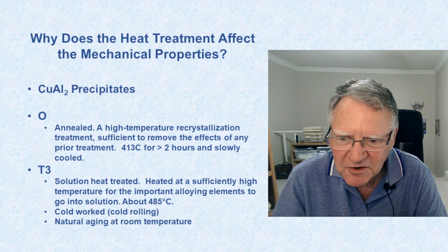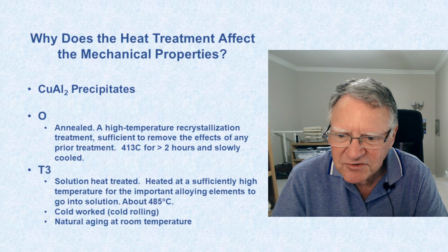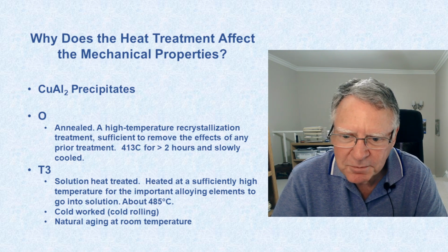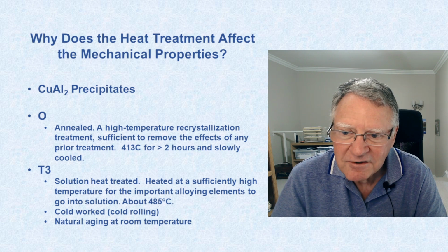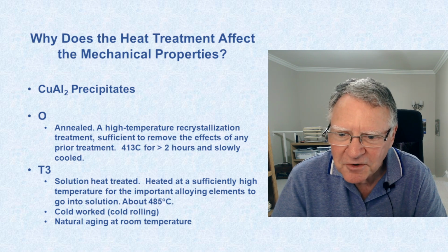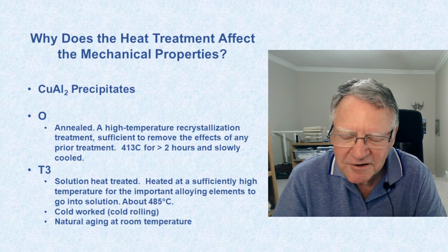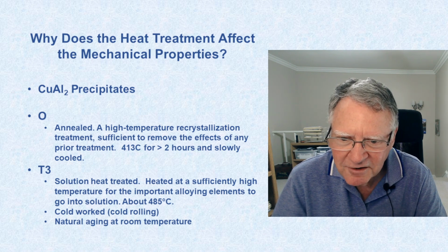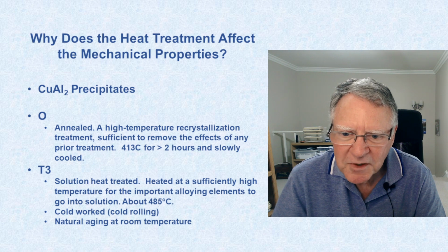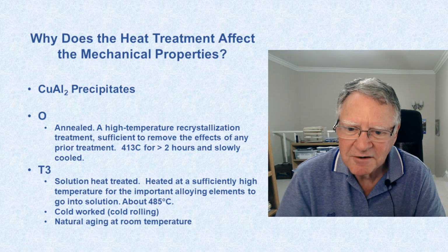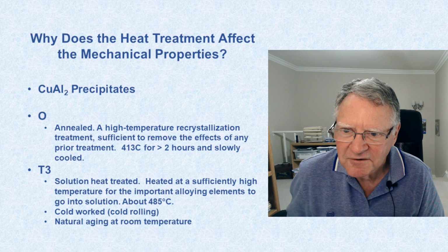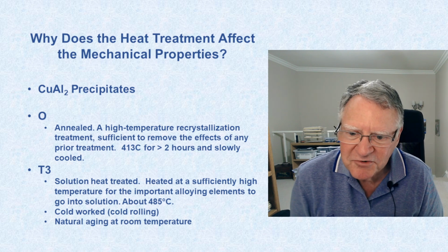So like I said, there's an optimum number and size of these copper aluminide precipitates. And so you just adjust your aging step, step 3 here. You just adjust the time and temperature to hit that optimum size and density of aluminum copper precipitates.